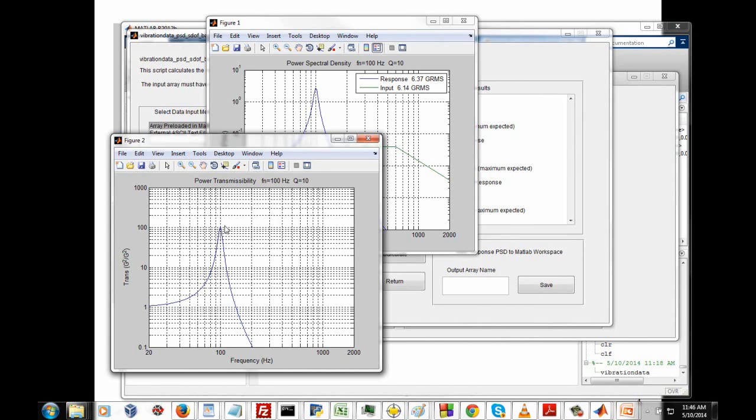But you've got to be careful with that rule, because that really only works for single degree of freedom spring mass systems. If we have a cantilever beam or a plate model or finite element model, or a multi-degree of freedom system with several springs and masses, well, that neat and tidy rule no longer works.